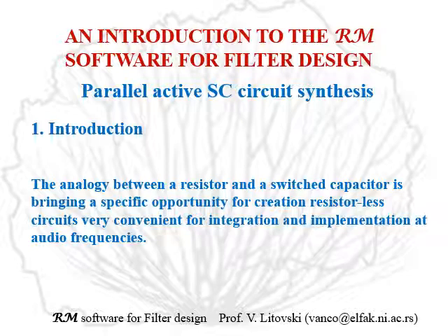The analogy between a resistor and a switched capacitor is bringing a specific opportunity for creation of resistorless circuits, which are very convenient for integration and implementation at audio frequencies. Namely, at audio frequencies, the values of the circuit elements, resistors and capacitors, become large.